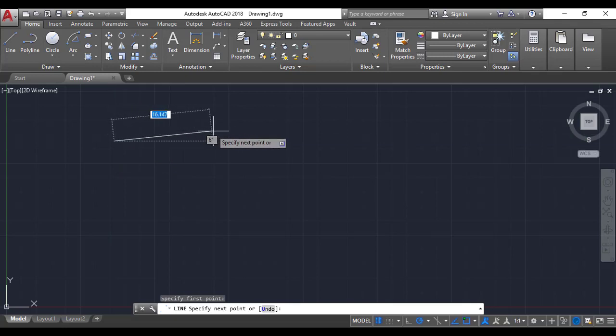So you can drag it to the right. You can set a distance, maybe let's say 20, and if you press tab, it will go to the next input box. There you can put in an angle, so you can put in 3 degrees, 5 degrees, whatever the case may be, but for now let's just leave it at 0.